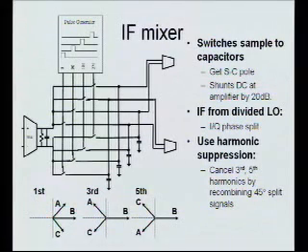And the basic idea is that when you shift the phase of a signal, of a sinusoidal signal, or any signal, if you shift the fundamental by a certain amount, its harmonics all shift by that amount times the harmonic number. So if you shift your wanted signal, or your fundamental, by 10 degrees, the third harmonic shifts by 30 degrees, the fifth harmonic shifts by 50 degrees, and so forth. Okay, the way we use that is we say, well, instead of using one signal, I'm going to use 3 signals, and I'm going to shift them by 45.